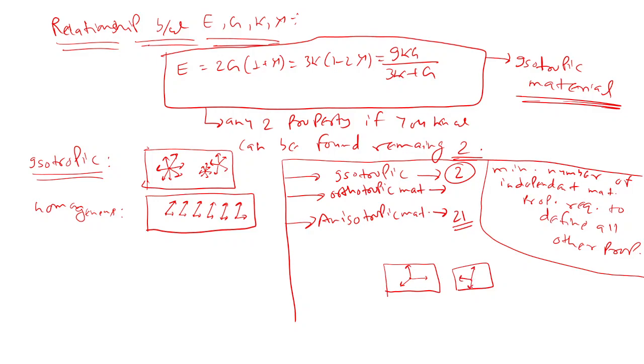Perpendicular, but in any orientation, it doesn't matter, in perpendicular directions properties are the same. Ortho means 90 degrees. So at 90 degrees material properties are the same. In that case the minimum number of variables is 9. So you have to learn that, if it ever comes up.